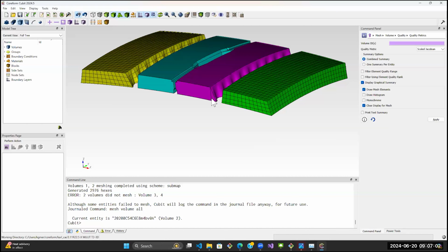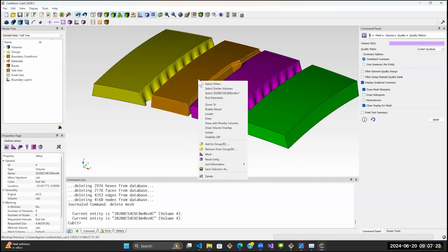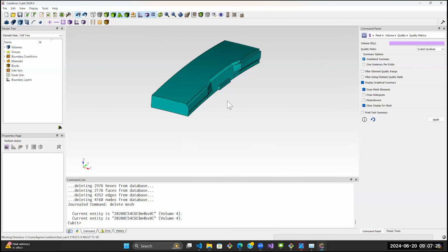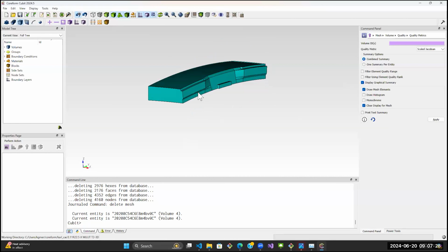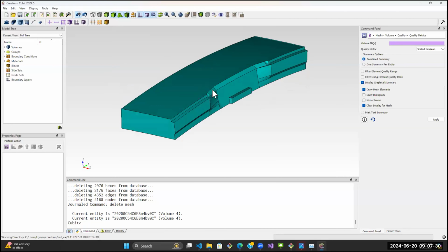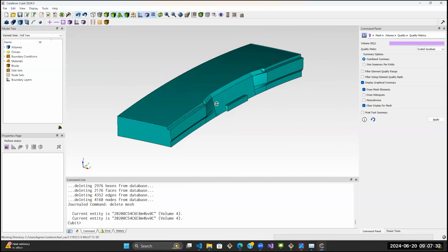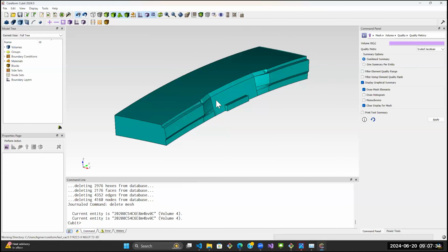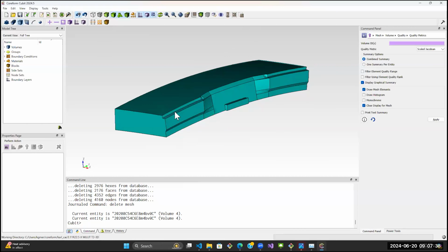In general, with tire meshes, we want to do a coarse mesh because we're going to use this mesh replicated many times. So these small features frequently we want to just get rid of. So let's do some compositing and some selection techniques to show how to get rid of that.